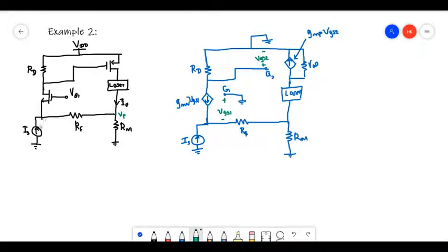And here we can see that this is the input current to the amplifier. So this is the source current, and current through this resistor is actually the feedback current, right? So we are subtracting this feedback current from the source current to give the input current. So this is how it works, right?